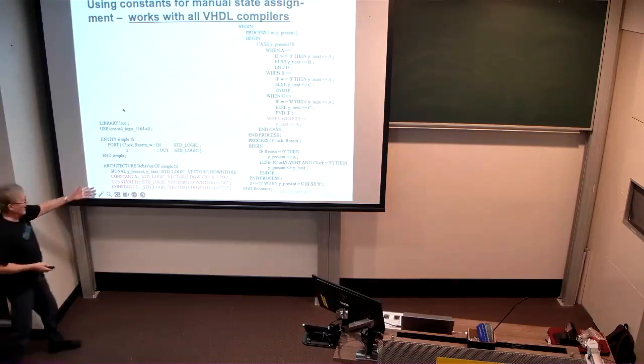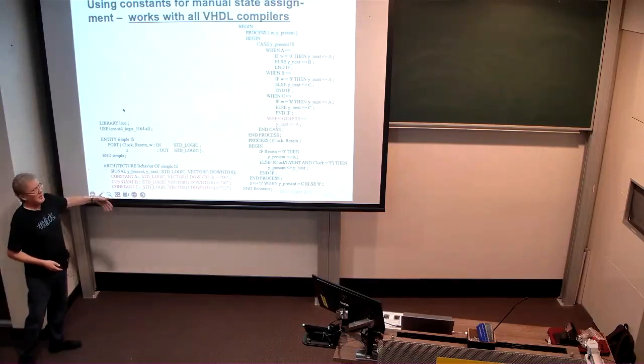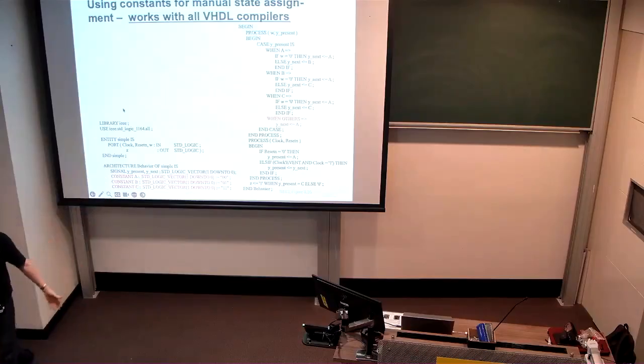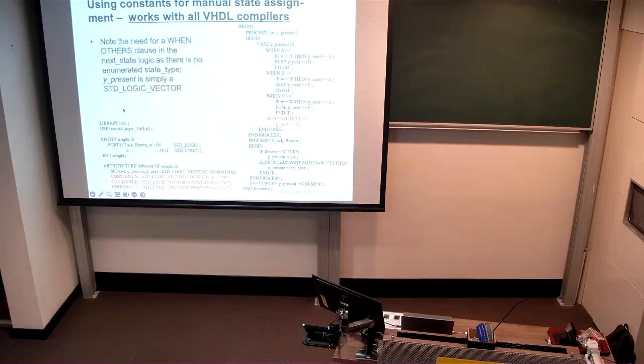I wouldn't advocate ever really writing VHDL this way. It becomes far more wordy. It's unnecessary. The tools are good. Let the tools do their job. Let them do it as well as they can. Depending upon what the target is, they will find the most effective way of implementing the code.